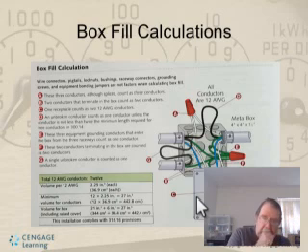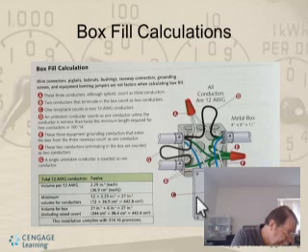And then you subtract all of the 12-gauge conductors, which are 2.25 cubic inches each, from the total amount. We already determined that the volume for the box is 21 cubic inches plus the 6 cubic inches, it equals 27.